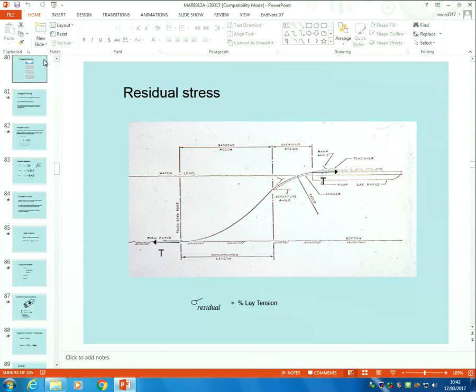Because that pressure isn't like a fixed boundary. If it was clamped, then that pressure stress would be transferred into the clamp. But it isn't. So it just increases. But it's balanced by the external pressure. So it's actually not restrained from expanding. It can expand.